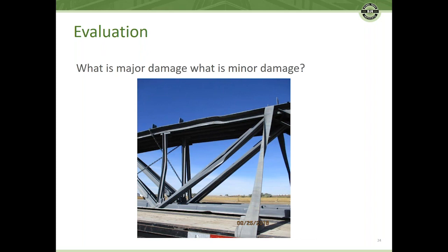Here's a slide we took not long ago as well. These joists actually were on a truck and were tipped over. The joist hit the ground, and you can see there's some pretty significant damage both to the webs and to the top chord. So in this particular case, the trucking company wanted us to see if we could fix them, and we said that because they hit the ground, there's a lot of things going on here that we didn't anticipate, and so the recommendation there was that they just get rebuilt.